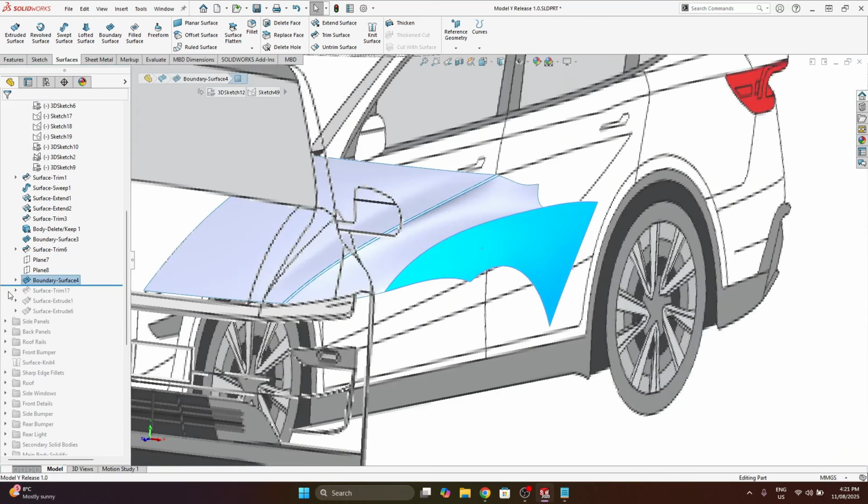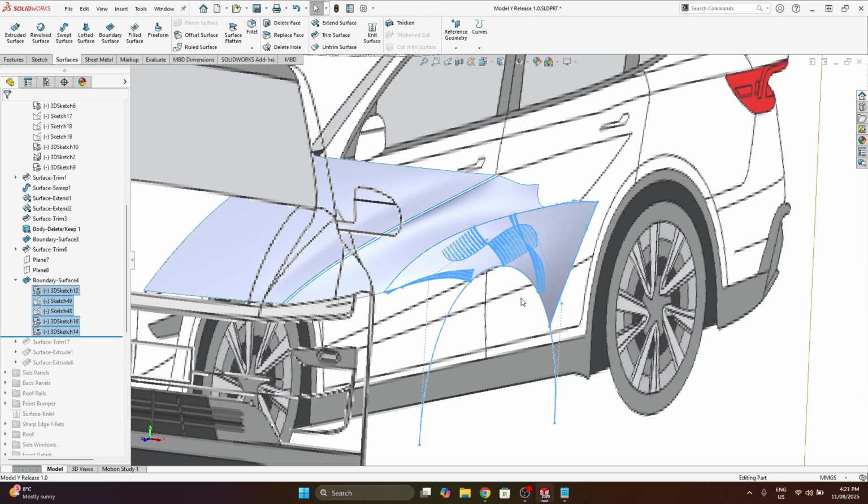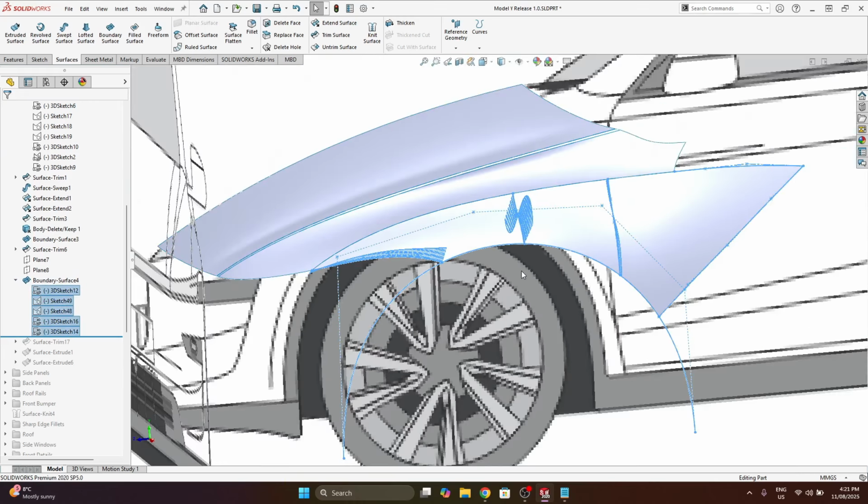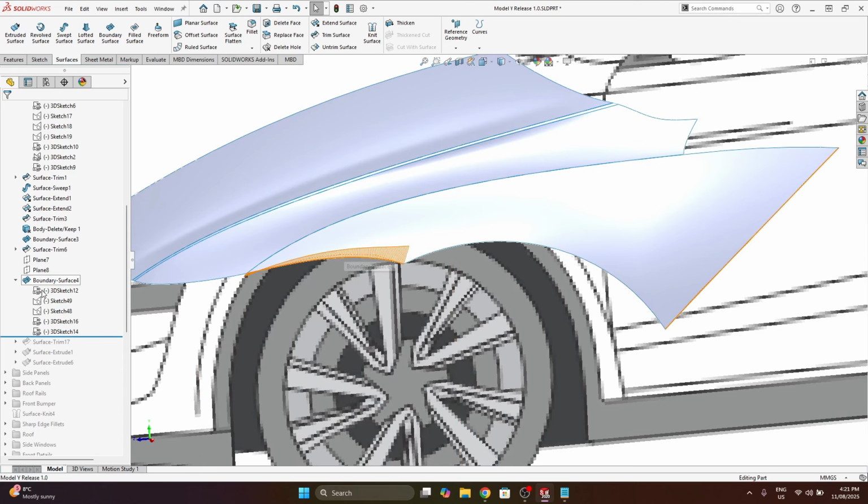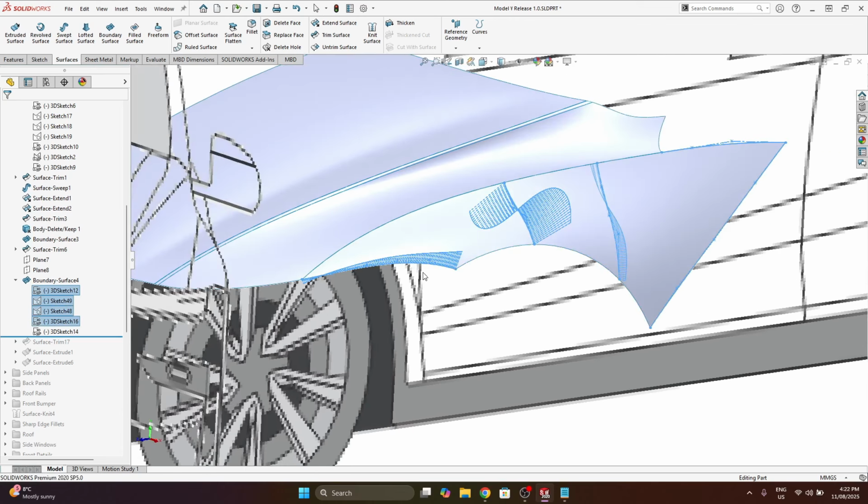Okay, going down to this surface now. So generally speaking, I have anywhere from 2 to 5 curves in one direction. What I mean by that is, if you're using any CAD software that uses NURBS, non-uniform rational B-spline surface modeling, you build your surfaces more or less as a square or a rectangle that can be slightly distorted. You have sets of sketches that depict the direction and they're perpendicular to each other.